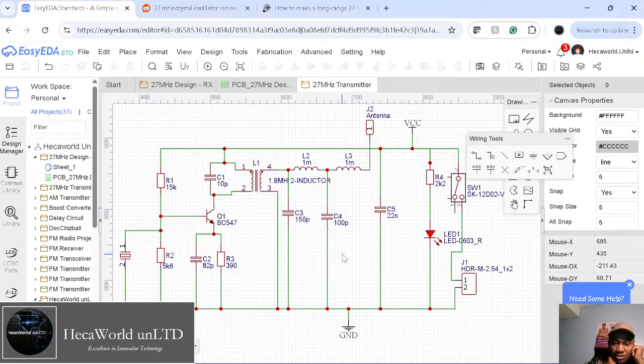So you need this filter to filter out any higher resonance, any higher harmonic. This is a low pass filter, so you can pass frequencies below 27, like 27 and under. Since the fundamental frequency is 27, it will pass 27. Maybe you can cut it off at even 30 or 40, because the next one is coming at 54.